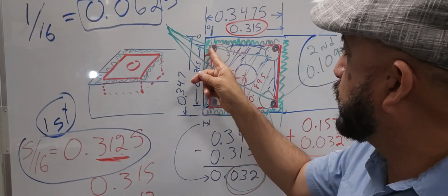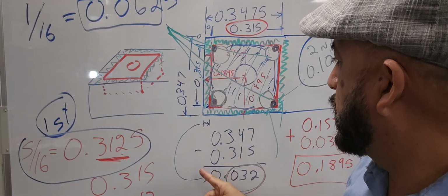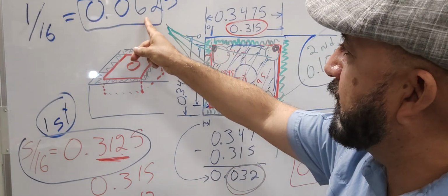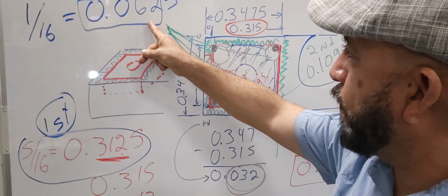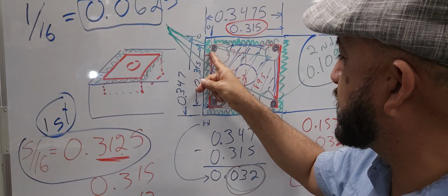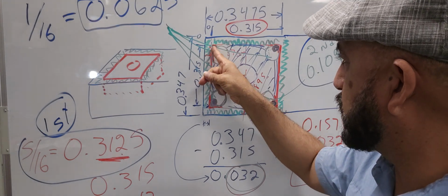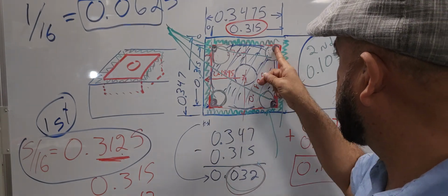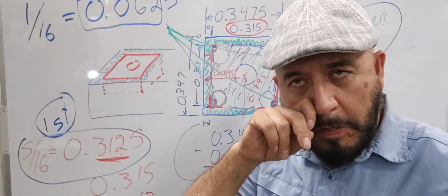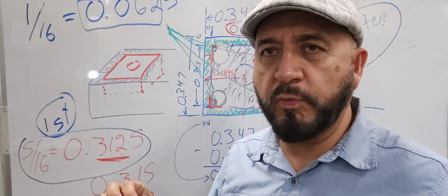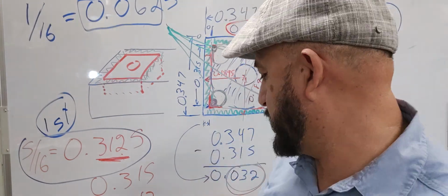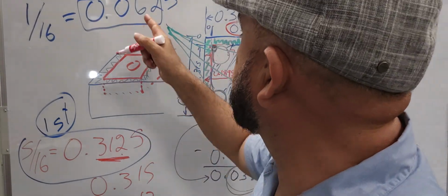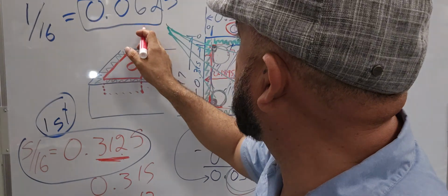And the only thing we have to do on each of these areas is move 32 away plus half of the tool. So let's find the half. What's the half of each of these tools? Because we need that distance plus a half of that to get into that little corner. And we also need the same for each one of these. All those numbers, we have to have them so that when we move our tools, we can go to those areas. Okay? So let's find out. What's half of 62? 31.